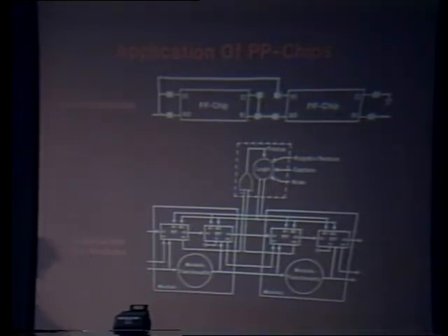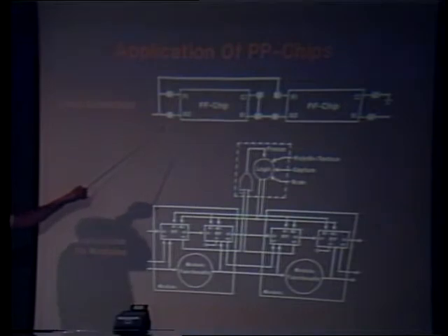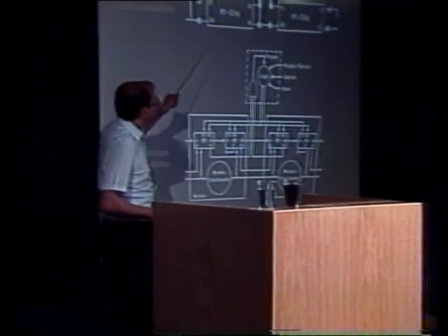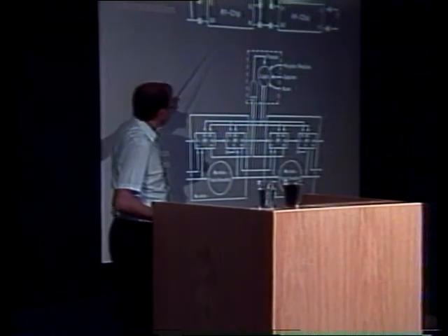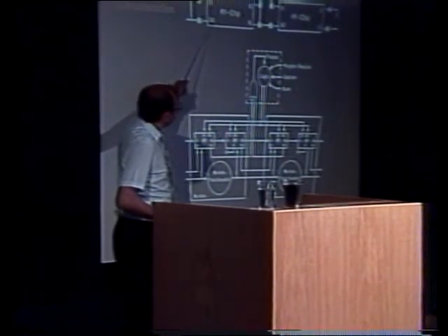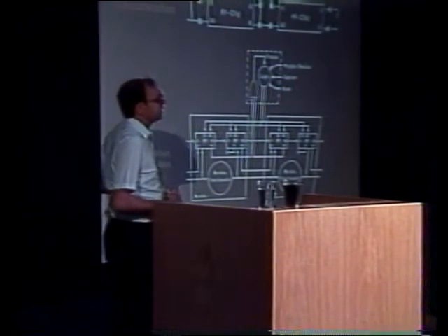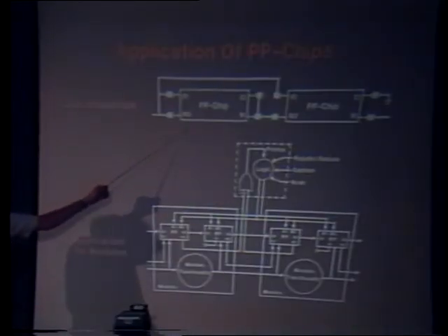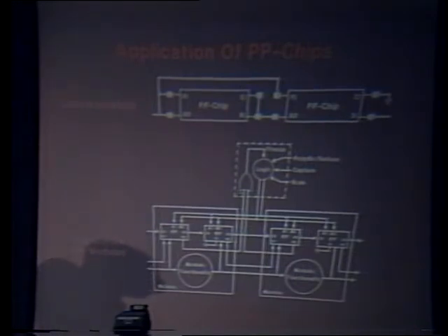Now, the other part of this expandable idea, or the concatenable idea, is to be able to put two or more chips together and make them into a larger linear feedback shift register. For example, in the self-test mode, this one would act as a 16-bit linear feedback shift register, whereas each chip alone is capable of acting as an 8-bit linear feedback shift register chip.